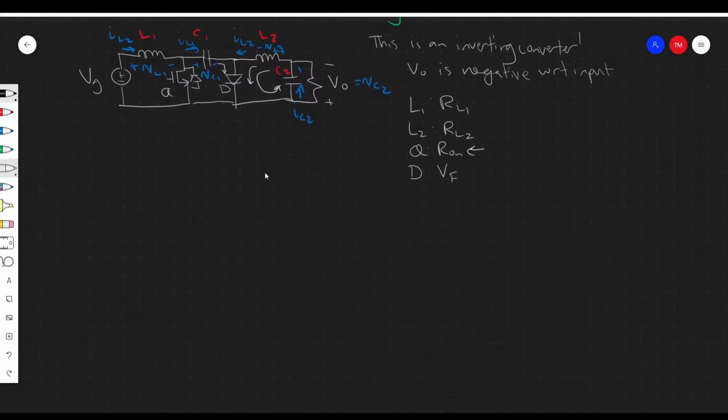So what do we do? Well, if we're trying to construct a DC model, we draw the converter in both switching states, write the inductor volt-second balance, capacitor charge balance, and input equations, and then from those equations, we construct circuits, which we then combine together using DC transformers to construct our DC model. So let's do it. From 0 to DTs, the first switching state.